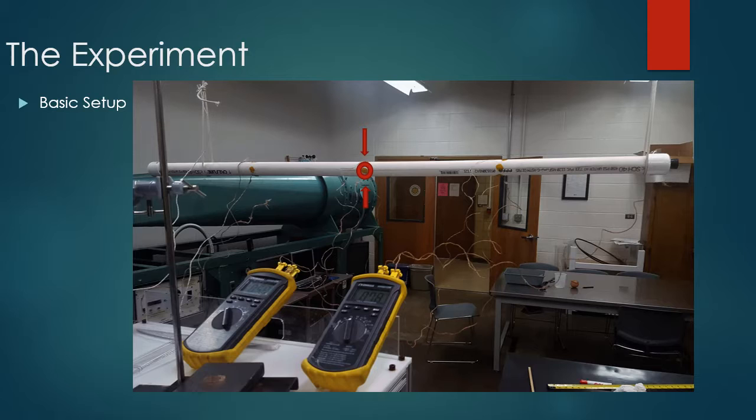This was necessary because a pipe undergoing free convection experiences uneven heat transfer rates. In our case, the center has the highest heat transfer and will therefore be at the highest temperature. The top is in the mid-range of the heat transfer, and the bottom is the lowest. For this reason, we took multiple measurements and averaged them.